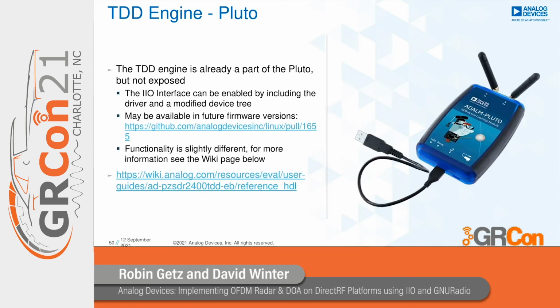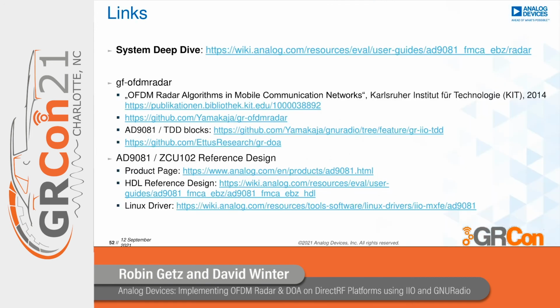What may also be interesting to you is that the TDD engine is already part of the Pluto SDR HDL, but it's not really exposed right now. So you may need to flash a custom firmware, and I opened a pull request which you can build yourself if you want to play around with that, which is available over here. For more information about how the TDD engine can be used with the Pluto SDR, I recommend you check out this wiki article, which will cover more of the implementation details of this entire system.